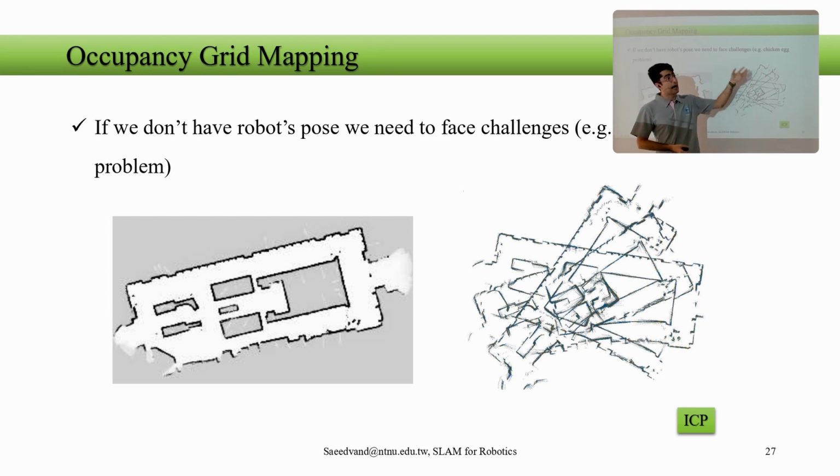So, not only can we use these techniques in 3D and visual SLAM based on 3D point clouds, but also after localization. You say, okay, I did my best with localization, I implemented the unscented Kalman filter or extended Kalman filter, I learned the math, I did everything as much as I can, and I did a lot to understand all this mapping, and I constructed the map finally, but the output is like this. Oh, my professor is going to be angry. Why is the output looking like this? It's not working. But this is common, so we add more layers to also try to match this construction of the map together.